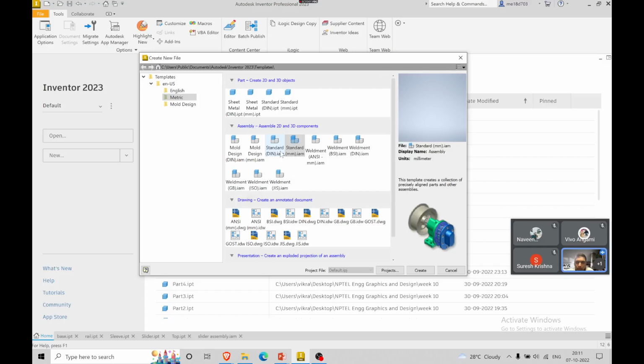Okay, so we will keep this one front view slightly below. Top view we will keep on the top. So we will select the projector, click this. If I click here, I right click, create. So I have got the top view now. So these rails, you can see top view I have created. This again I will slightly bring down.